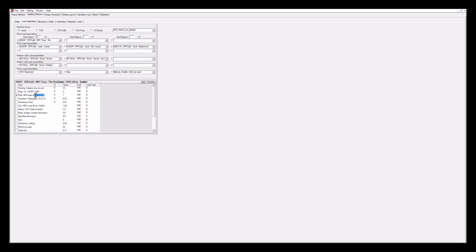the name as well. So if I wanted to adjust this to be 16 inches, I can change all that. As long as I make a change and then I click apply changes, it will adjust it for this model. So I can go through and adjust any of the different kinds of loads I want. And so I'll click on this one. I can change this to be, for example, 3 pounds, and it will adjust and automatically update. As soon as I push apply changes, it'll update that force for me there.